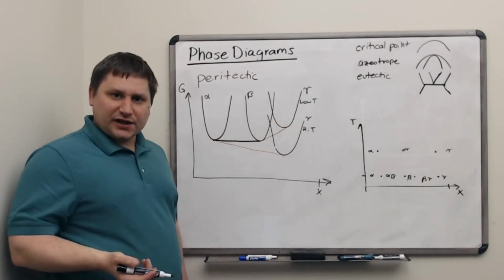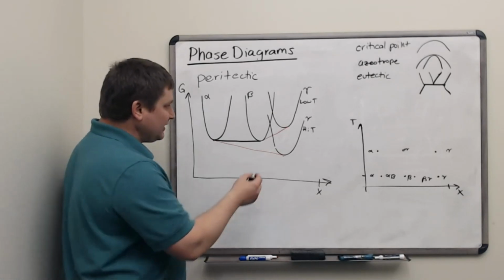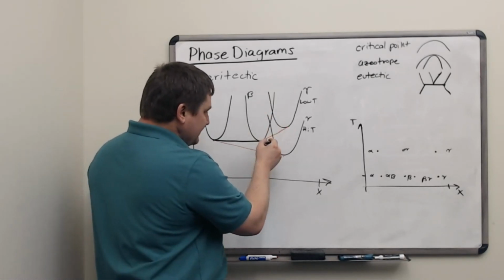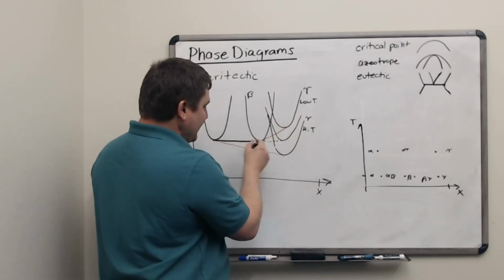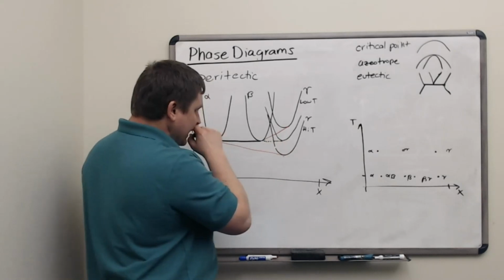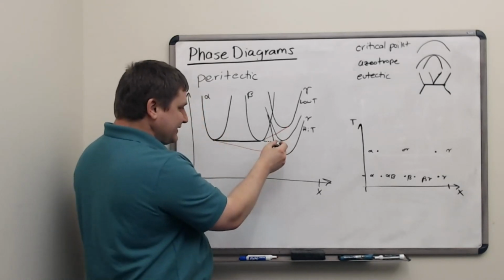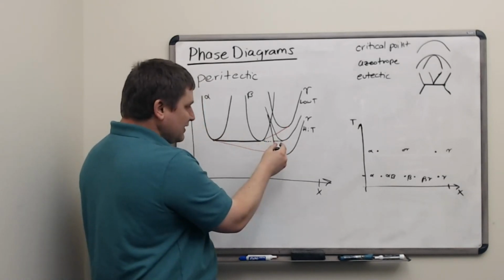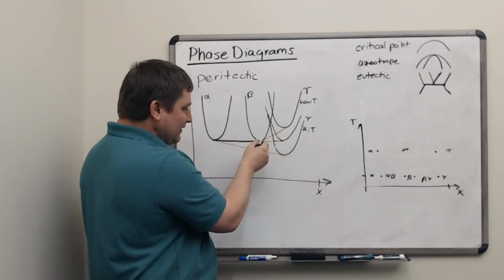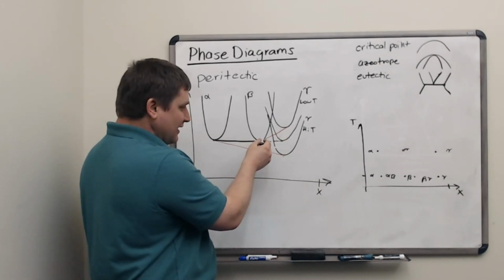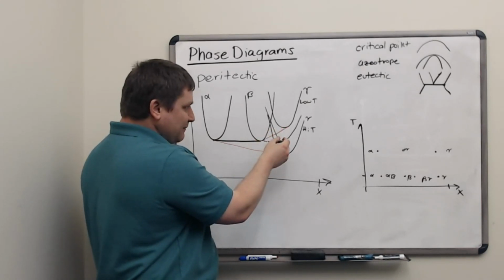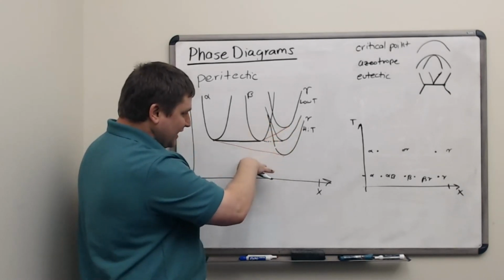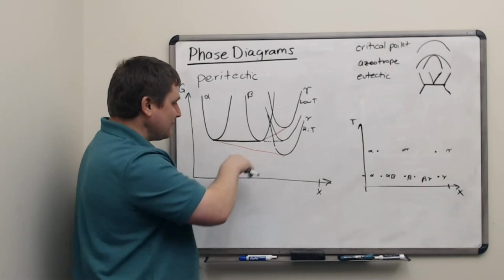So the critical point here for this type of behavior is really when this gamma curve comes down to be directly tangent to this alpha beta line. And at the instant that that happens, at that specific temperature, there's a line between all three peaks. Just below it, there's a possibility of some beta sneaking in there, right? And some mixture between beta and gamma. But as soon as this gamma curve drops below, it sort of lifts this line off the beta peak and the beta disappears completely.